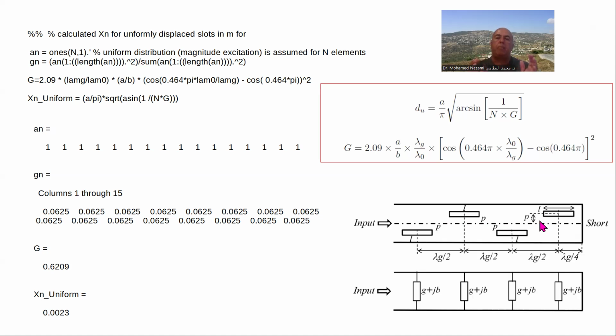Now, with that, it's a rectangular window of excitation, and therefore the sine x over x radiation pattern is going to have a side lobe of exactly 13 dB, just like you would expect, because it's non-windowed. This is not tapered. So this is pretty easy. I'm going to start with this, and then I'll come back and do a Chebyshev tapered one.